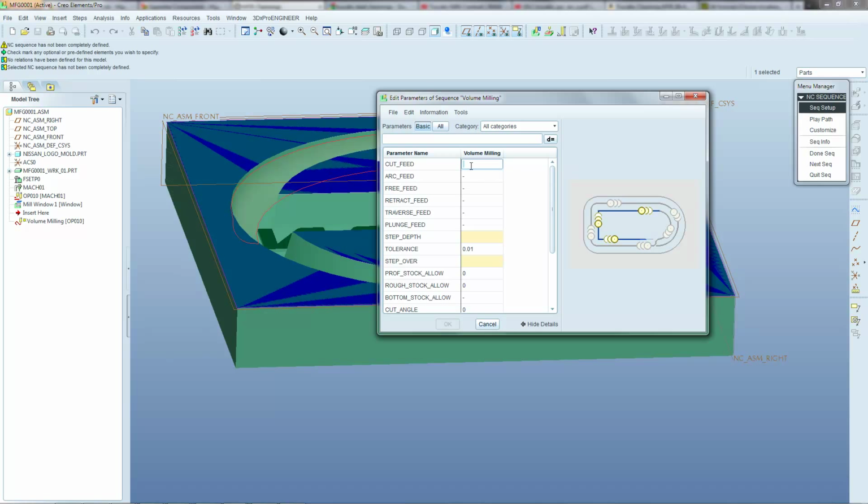This tends to be in X and Y. The greater this value, the more stress the cutter will be under, the more stress the machine will be under, and probably the higher the temperature reached at the cutting tip. So this has quite large implications for tool life and the efficiency of the cut that you're taking.